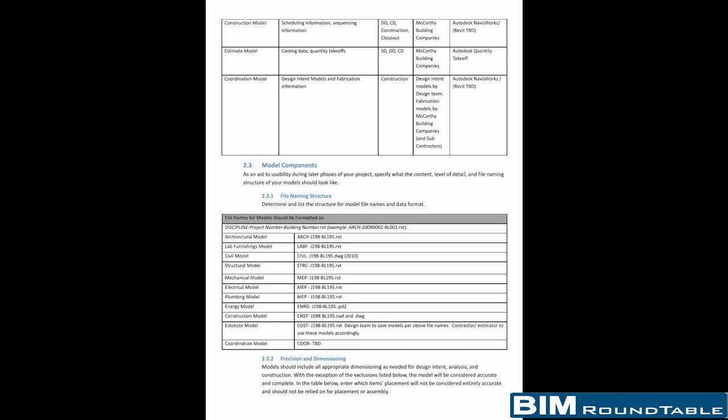You did it in 2009 and try to upgrade it in 2015, really? You've got to go step by step. You can skip a couple, but you can't skip very many. You can go from 2009 to maybe 2011, but you can't go from 9 to 12 or 13 because it'll kill it. They've changed a lot within the coding, from what I understand. Subtle stuff that you don't see, but that Revit itself sees and will cause lots of problems. It's also good for corrections, because I've had 2008 and 2009 models that have a corrupted element in them, and I can't do anything with the model.